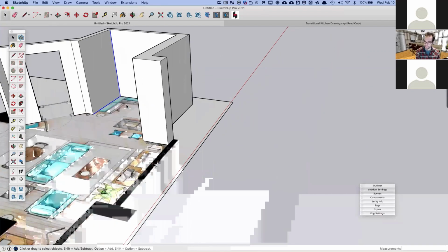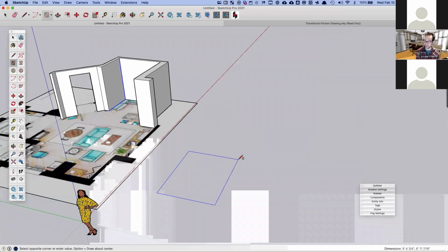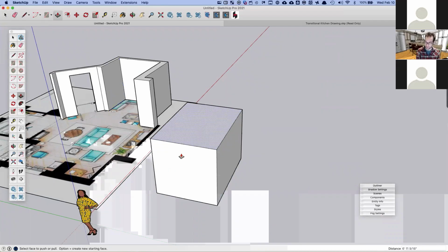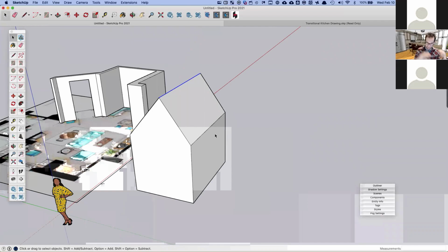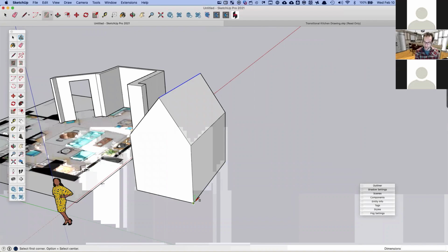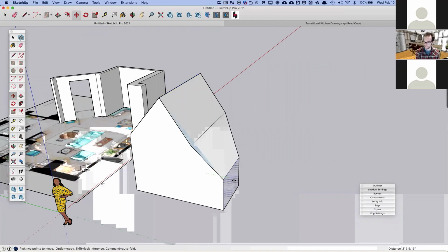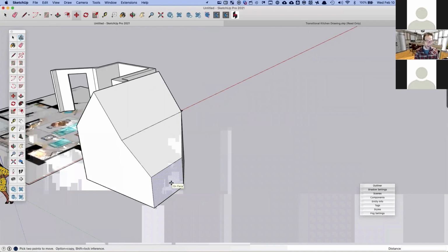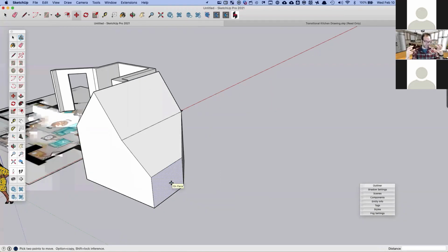SketchUp at its core is a fast architectural modeler. And what that means is when you make stuff in SketchUp, you can very easily stretch and pull geometry to make basic architectural shapes. It's sort of in its DNA. And part of that functionality is the ability to stretch and pull things like this. So whenever you make stuff and that stuff touches other stuff in your model, it will have a tendency to stick together like I've shown here.